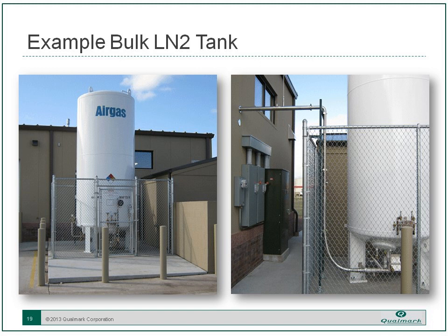And here's a photo of an example of a bulk tank installation. You can see here vacuum jacketed piping coming up and into the facility. And this is what will keep you from having ice balls outside. Here in Colorado, we don't have to worry about that too much. I think today we're supposed to hit 10% for humidity. That's why all the fires are burning so well. But in other places, you do indeed have problems with ice balls, and if you go with the liquid nitrogen piping, those problems go away.